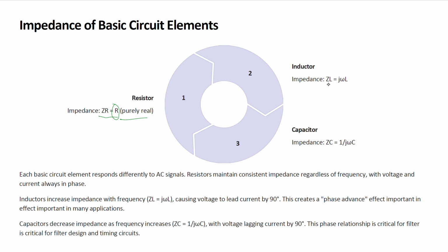The imaginary part, if it's an inductor, is j omega L, and if it's a capacitor, is 1 over j omega C. So this is how we can transfer the capacitor and inductor, which are integral-differential components, into the phasor or frequency domain, and have only an imaginary number as a coefficient. As you can see, it would simplify our analysis between V and I to the simple Ohm's law, where V is simply Z times I. Now Z is a complex number.